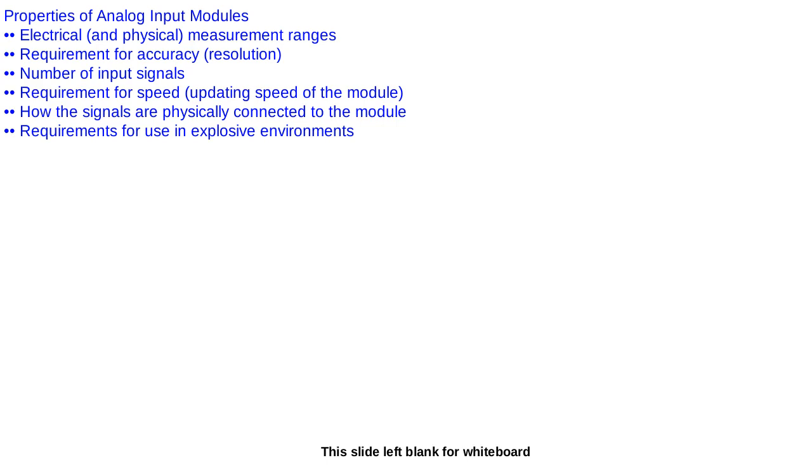So how much dust or temperature, etc., will this input module tolerate, and how much will the individual inputs tolerate? That is another property to consider when selecting an analog input module. Another thing to consider is the linearity. When you talk of linearity, this means: is your module going to be linear across the entire range of measurement? That can also be a property to consider.